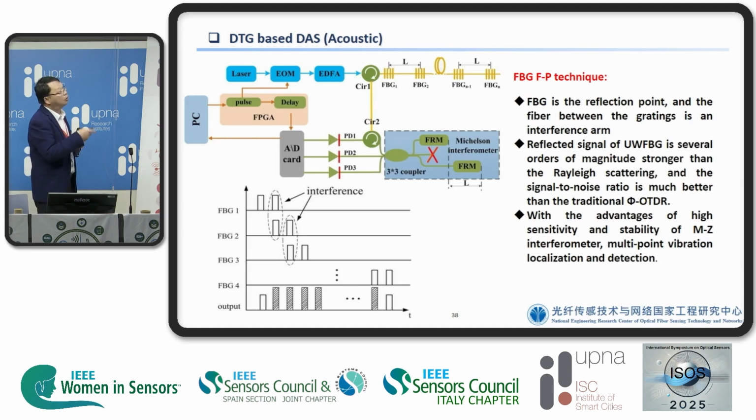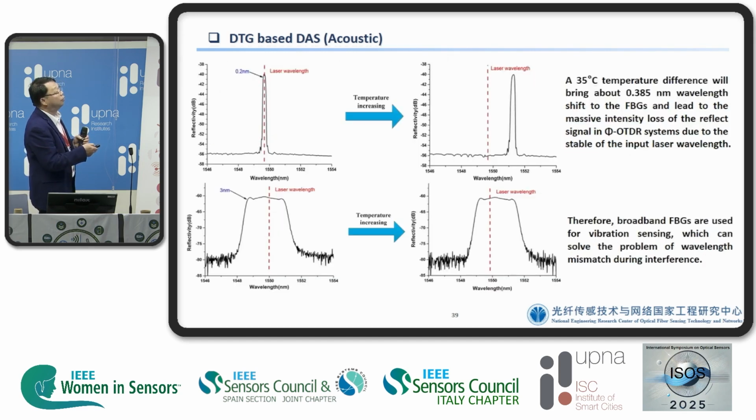Okay, that's how I go to the acoustic sensing. So how can we use the acoustic sensing? Actually, we know that the FBG array, we keep the distance in between. If the distance between is changed, or there's a phase shift here, then the two FBG arrays can have the interference, and then we can monitor the interference or the phase shift from the two areas, and then we can get the distributed acoustic sensing measurement. This I'll also show you.